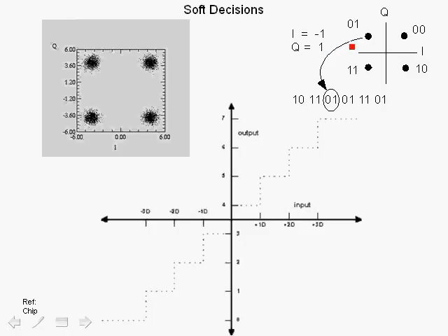So far we've been talking about hard decisions in our Viterbi decoding. When we discussed the example with a Viterbi decoder, we mentioned using Hamming distances, and Hamming distances imply the use of hard decisions. In the case of hard decisions, for example, if we receive the constellation shown here for a QPSK system, we receive a noisy constellation point. These are the actual received constellation points. The ideal constellation point, of course, is at the middle here.